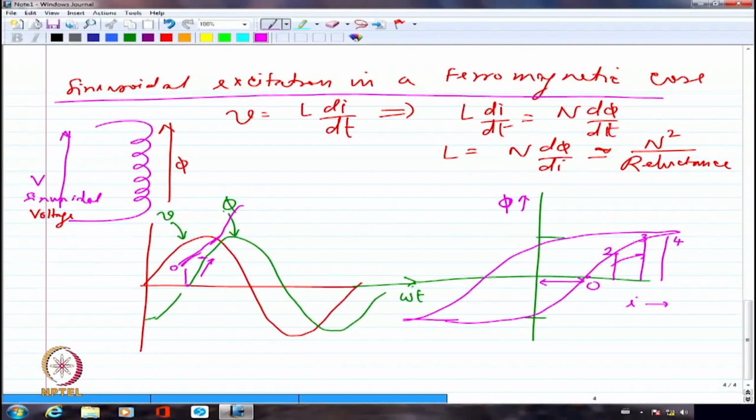So, I am going to have the current almost reaching the peak, and after that it will probably drastically decrease also, because if I look at this portion, the flux is still fairly constant, but I am trying to reduce the flux. But the current will actually decrease quite a bit without making a dent on the flux.